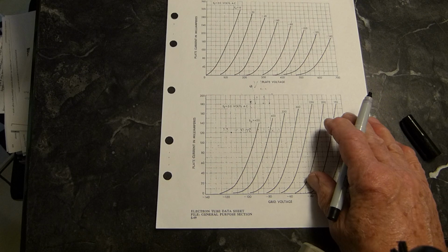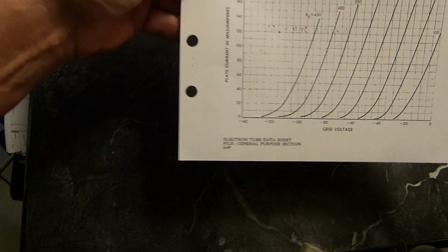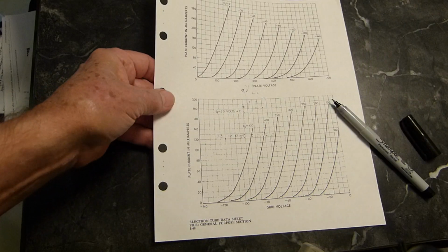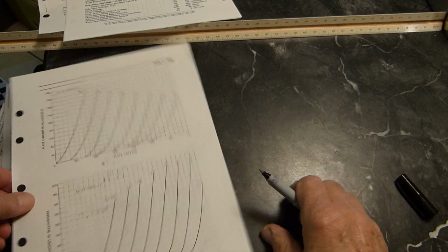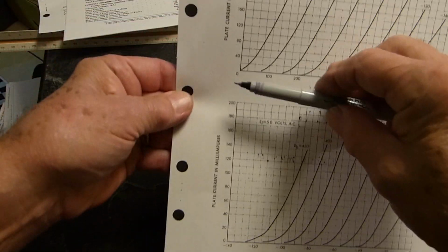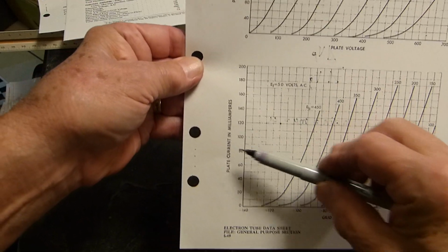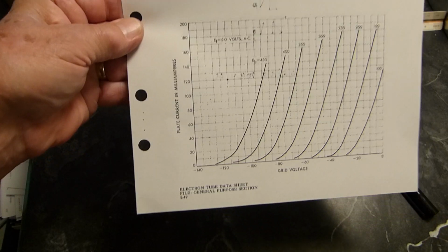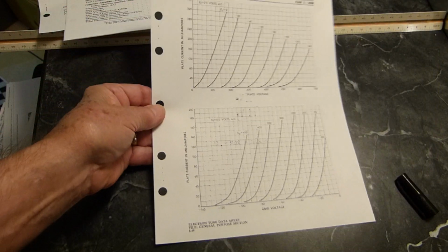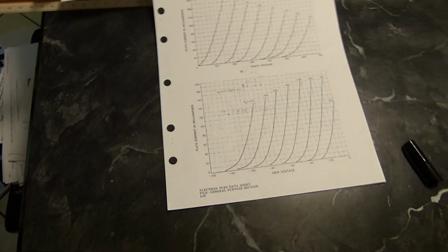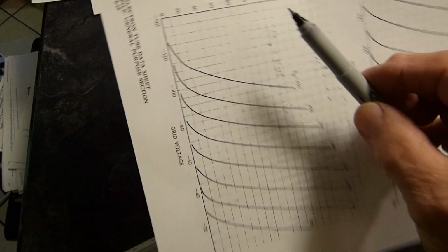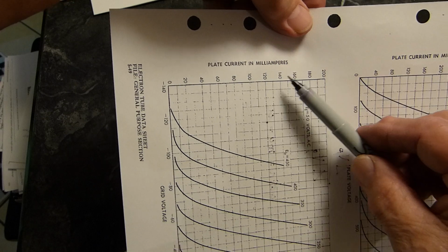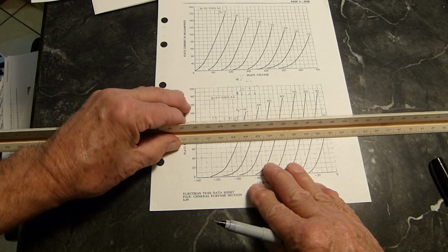So what we do is we look here on the graph that has plate current. I've got to move my camera just a little bit. I keep wanting to get too close here. It's got to have plate current on one side because this is a constant. We're just going to draw a straight line across from some level, and we determine between like 60 and 72. So 60 and 72. I don't know. Let's choose 70. See right here. Plate current in milliamperes. We're going to choose 70 because that's about in the middle. Doesn't have to be in the middle, but you know, you want it to be. We're going to draw a line straight here.